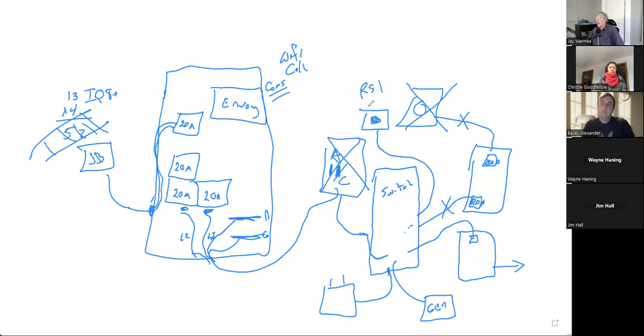So then you've got to have a DC disconnect, this rapid shutdown initiator. As soon as they push that button, then essentially it turns off all power in your system. So everything is turned off. And that's the point of that. It's almost like a panic button out there. It just turns off your batteries, your generator, all loads. So really in this situation, there are 3 different switches that need to be turned off in order to ensure that there's no power going on anywhere in the house.